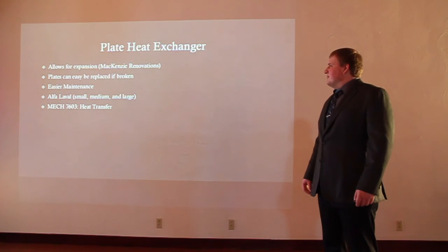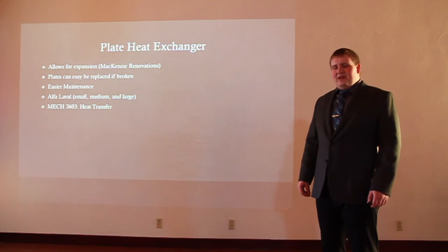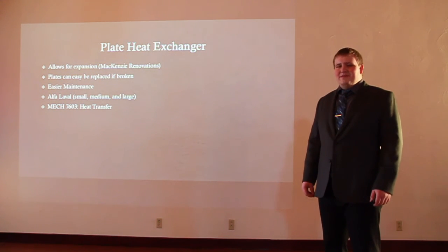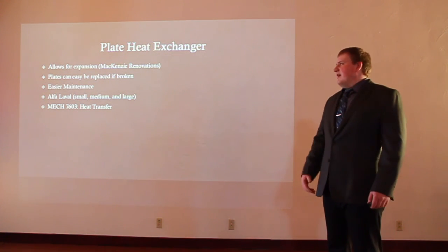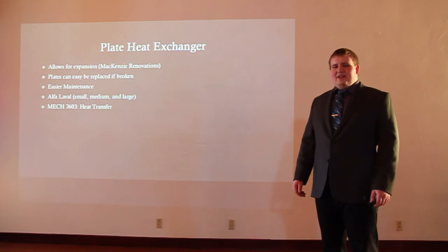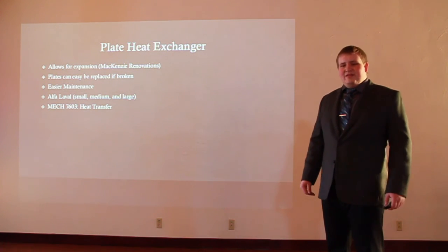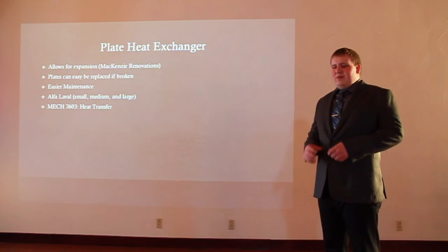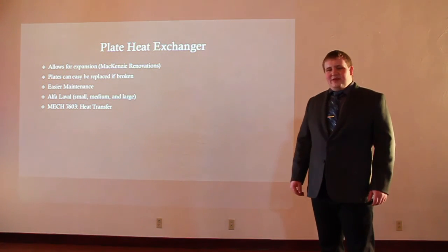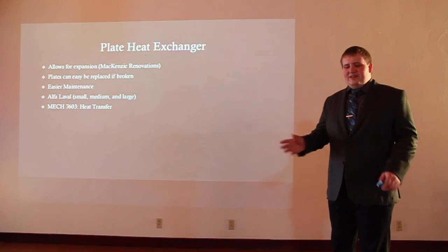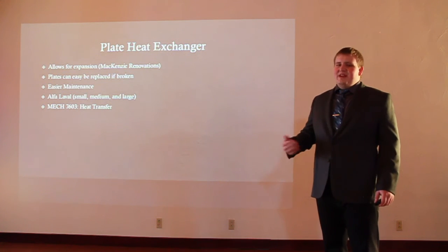The next technique I'm going to be looking at is plate heat exchangers. There are a few reasons why I wanted to do a plate heat exchanger over any other type of heat exchanger. One of the reasons is it allows for expansion. Right now, the Mackenzie Residence Hall is going under a lot of renovations, and they might retrofit in a different heating system, and this allows for expansion of that heating system. The plates are also easy to replace. If one gets broken, you can slide any of them off and replace that one very easily, and they're also easy to maintain and easy to clean.